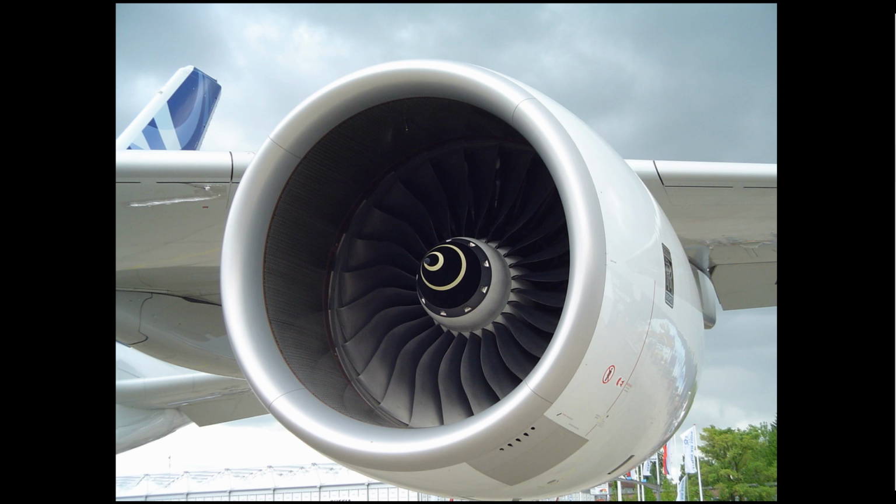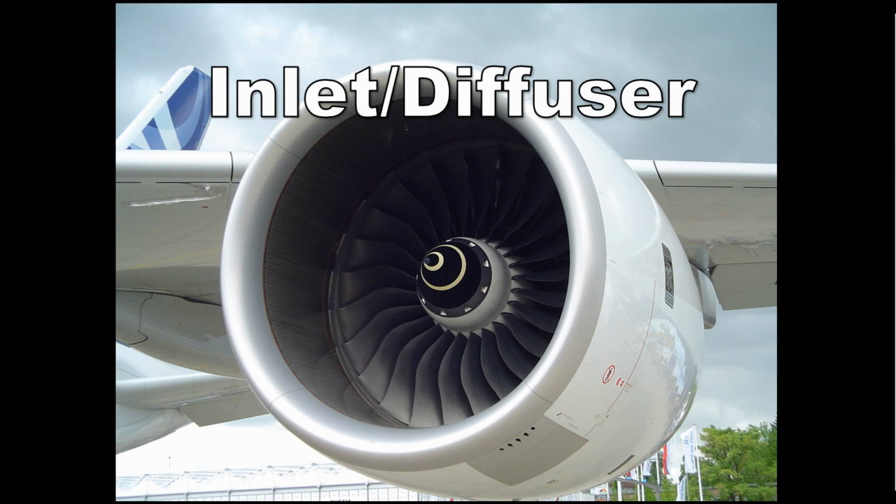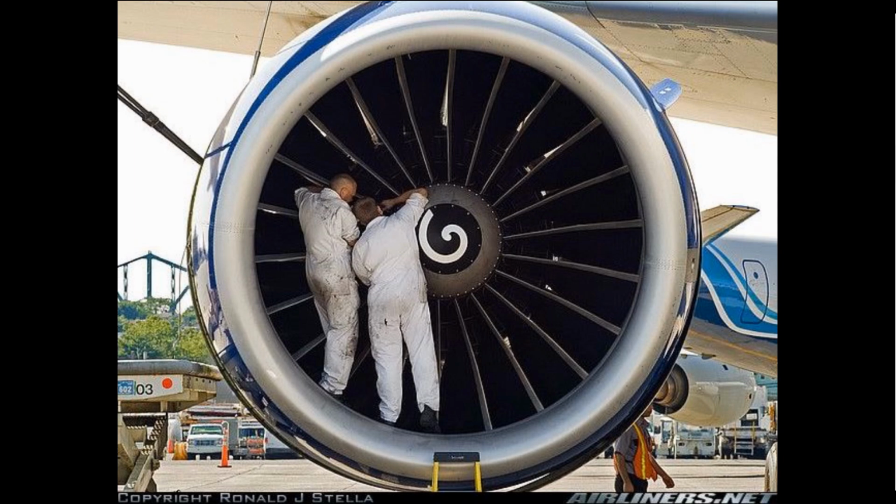If you look at any turbofan engine on a civil aviation aircraft, you'll note that the big fan is actually recessed back into something called the nacelle, which is essentially the outer casing of the engine. So if we're talking about components of the engine, the part from the front plane of the nacelle back to the front of the fan is called an inlet or diffuser. If you look carefully at an engine, you'll see that the nacelle actually widens out from the front plane back to the fan. We'd like to solve for the minimum diameter or throat diameter at the front of the nacelle.